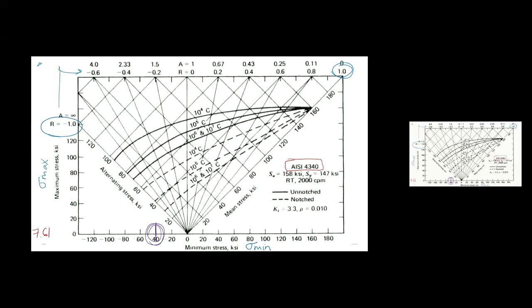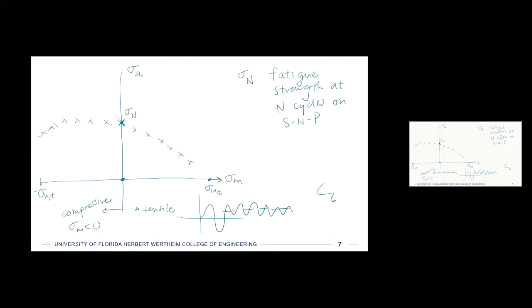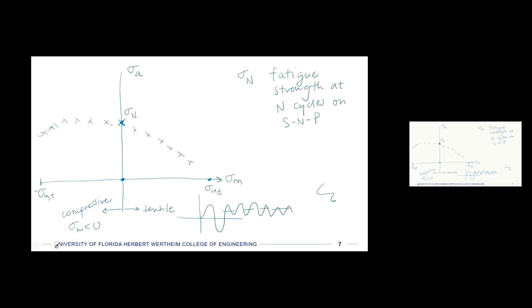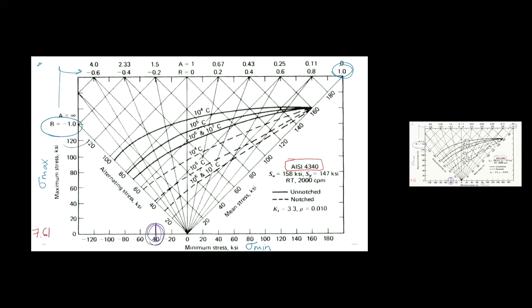And then my maximum stress was higher than that. Let me go back to the chart so I can just estimate. Okay, so if my sigma min, let's call it 40 kpsi, it's about 3 times higher than that, so maybe my sigma max is like 120. So then that's on our y-axis here. If I go up on 40, over on 120, I find myself at this giant purple circle in the center here, right?